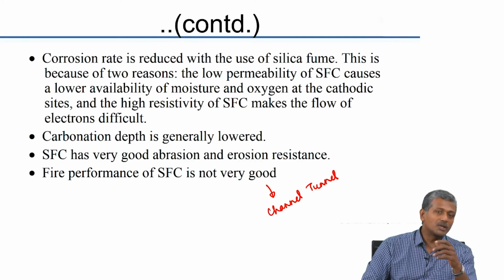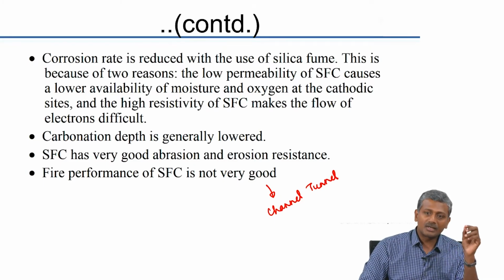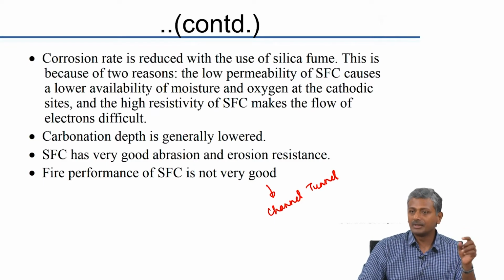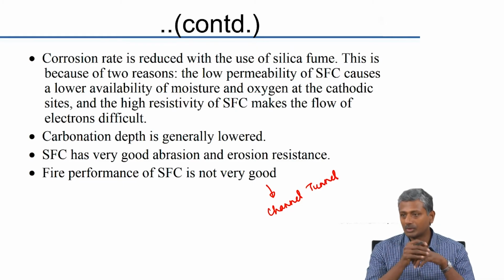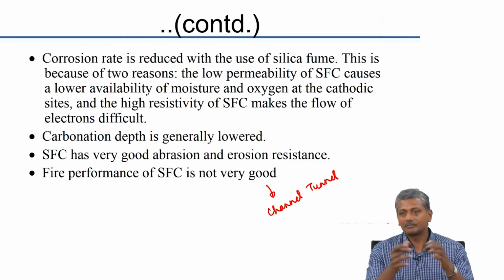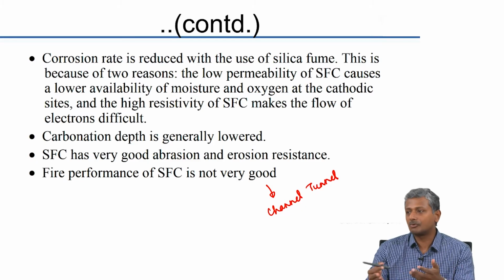Okay, what people started doing is looking at how we can learn from this and make silica fume concrete also fire resistant, in which case what they did was they started putting plastic fibers in the silica fume concrete, and what happens is at the high temperature the plastic fibers would melt, leaving behind the voids, and then the water will be able to come out as steam through those voids. But again, we do not really worry too much about fire performance, except this is an extreme event obviously which generates this level of fire. We do not really give the kind of emphasis that is happening in this particular case for fire performance.